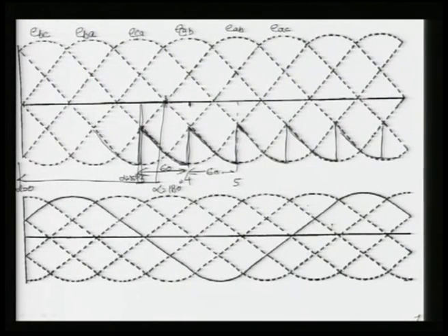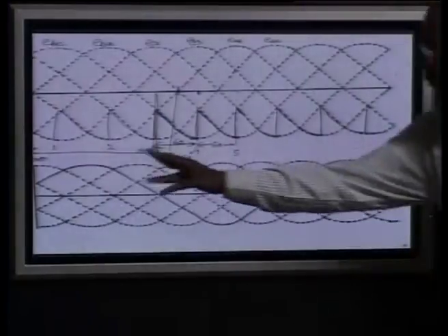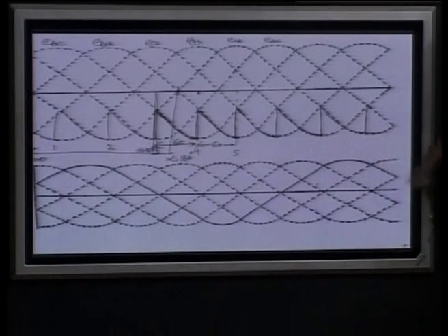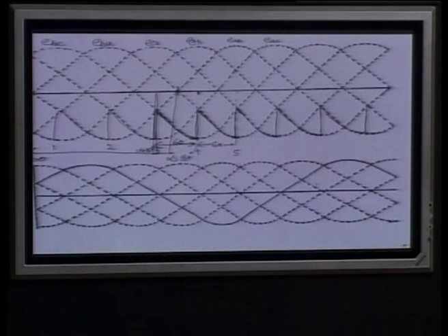it was going like this and like this. So, it was 3, 2 and 1. You can also verify that this will be the output voltage, because 3 again 1, 2, 3, 4, 5, 6, 1, 2, again it is going to be in cyclic order. So, this is your output DC voltage which is appearing across this in case of inverter mode, and we have taken alpha is equal to 150 degree.